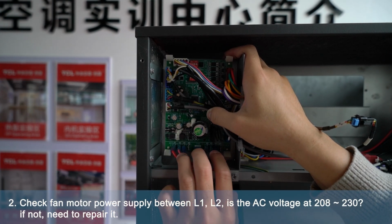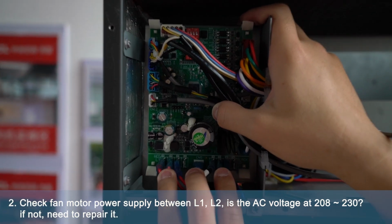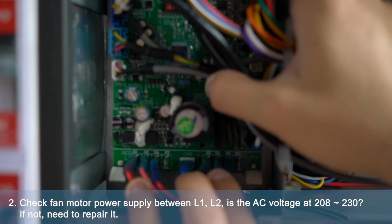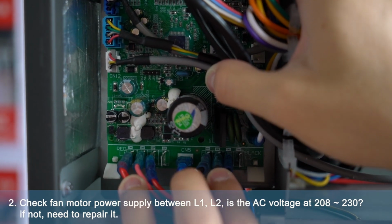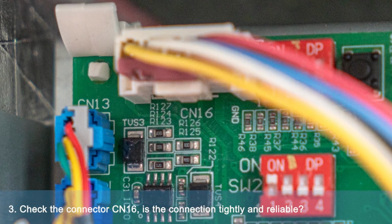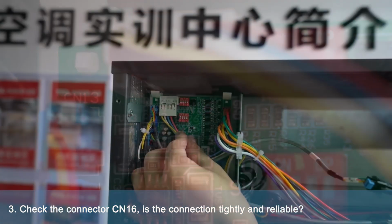2. Check the fan motor power supply between L1 and L2. Is the AC voltage 208 to 230? If not, need to repair it. 3. Check the connector CN16. Is the connection tight and reliable?